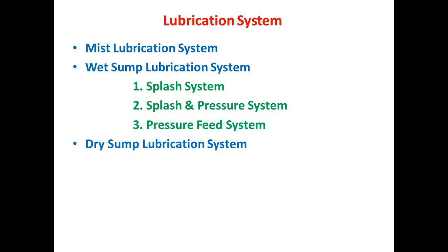Generally, the advantage of such a mist lubrication system is that it doesn't require any kind of pump, filter, strainer or any kind of pressure regulator valve. So that's why it is quite the simplest lubrication system. But along with this, it has certain disadvantages.